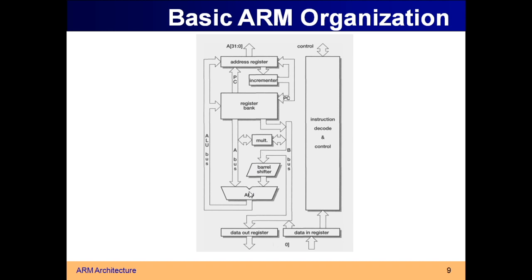For example, if you want an address to be incremented by 10, you can perform that operation in the ALU, and the resultant address can be written to the register file where the PC is present. So the program counter itself is a part of the register file. What do you mean by program counter? The program counter is a register which points to the next instruction to be executed.